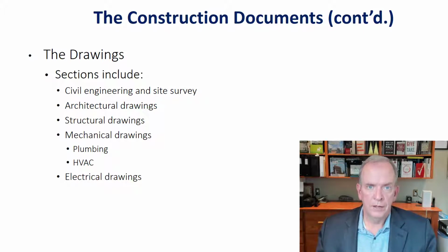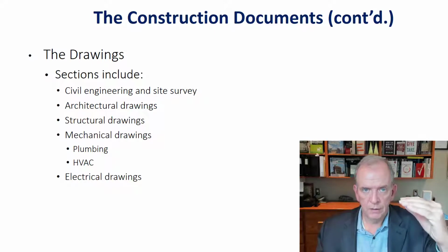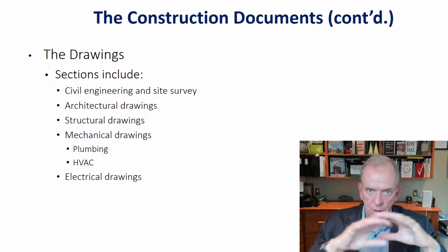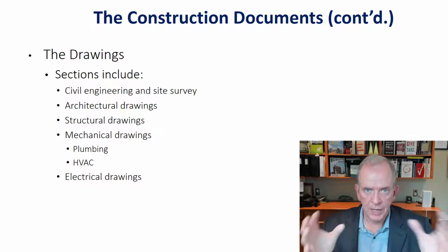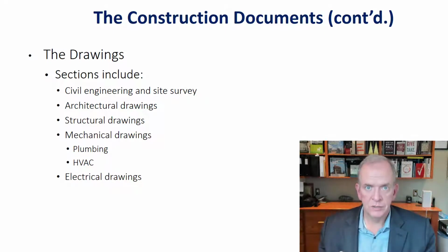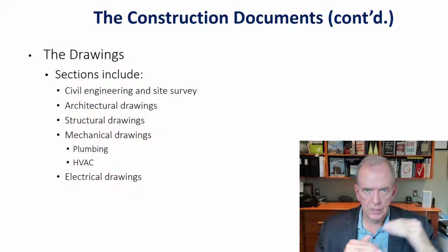Then, if you're successful for the project and now you're constructing it, you'll be following the approved construction drawings for the project. You'll be following along with your contractual requirements. That's at the highest level. Specifications take precedence next after the construction contract, and then the drawings next after that. And we just mentioned in the previous lecture how the conflicts work.